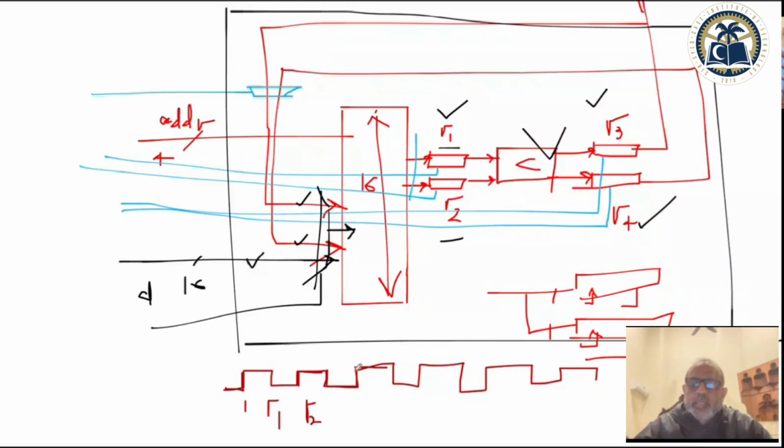So in this clock cycle, you can store both the values in the R3 and R4 registers, because the comparator has two inputs and two outputs. Now in this clock cycle, we are not trying to optimize, it's just a first attempt. I'm just saying how it should basically run.